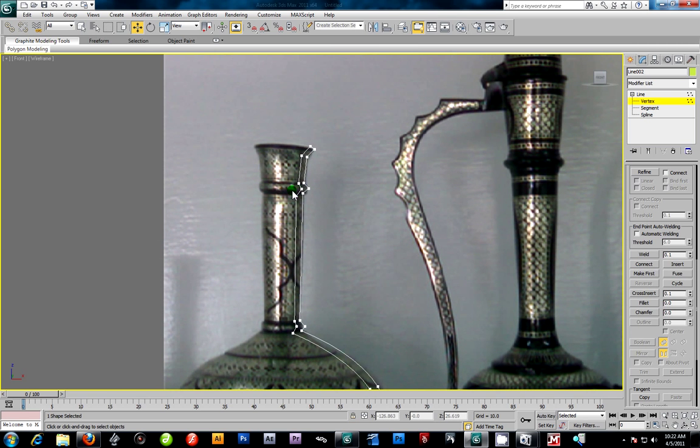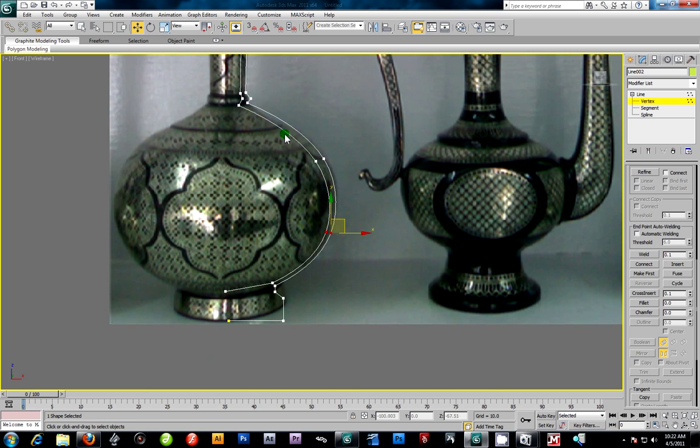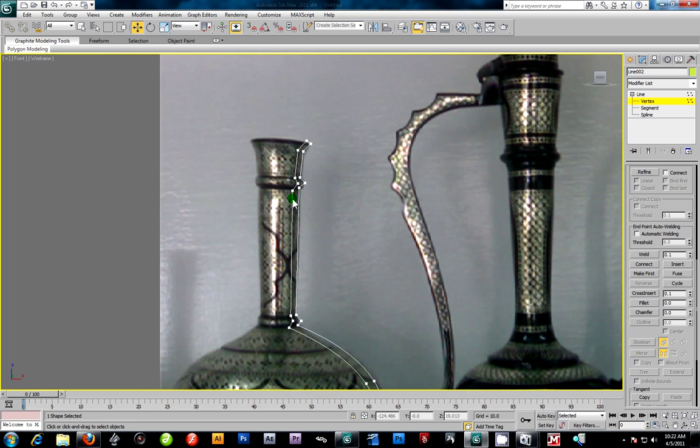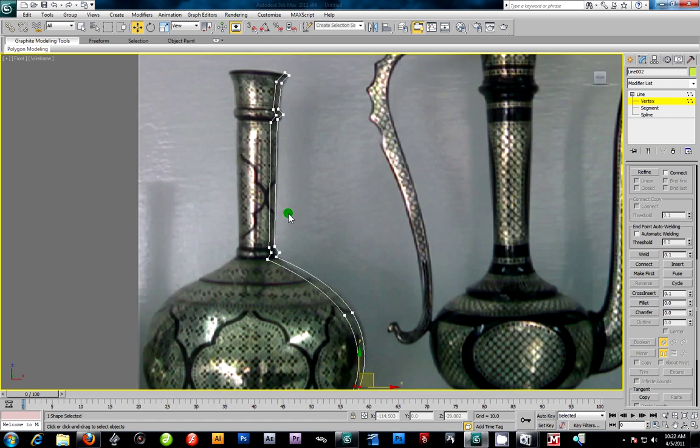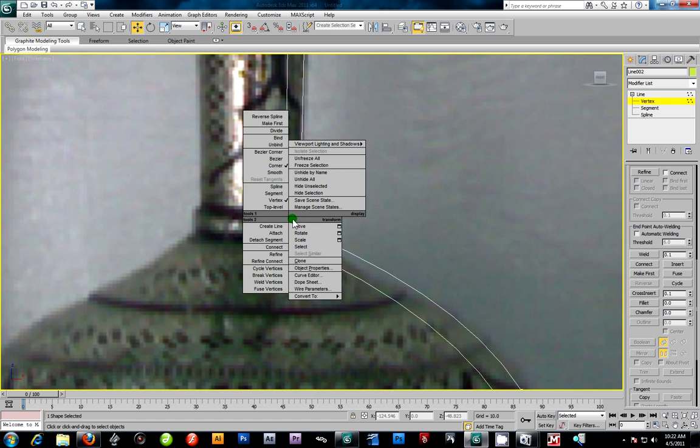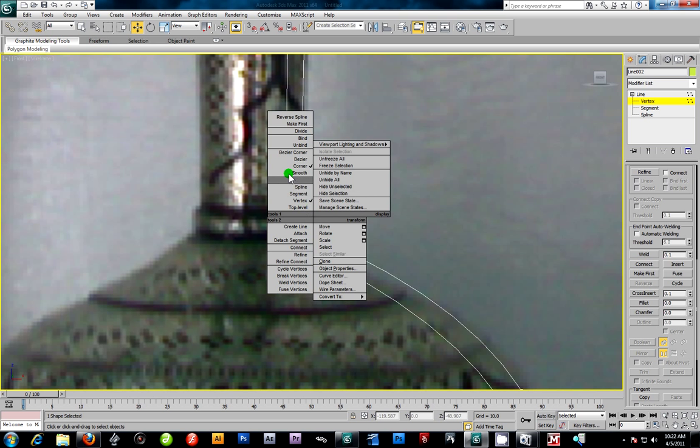Alright, let's see. Okay, from here, I can easily come in here and right click all three of these, try to smooth them out, but obviously that didn't work, so Control Z. How about I just grab these two middle ones right here, right click, and smooth. There we go. And then I can just grab each one individually and shape it up, which I'm doing right here.